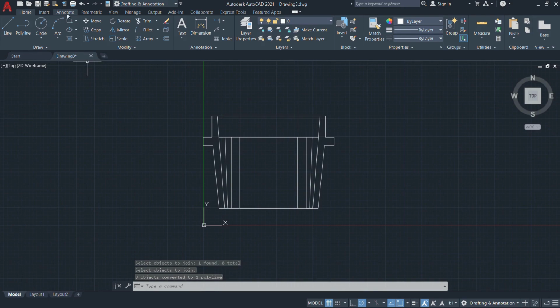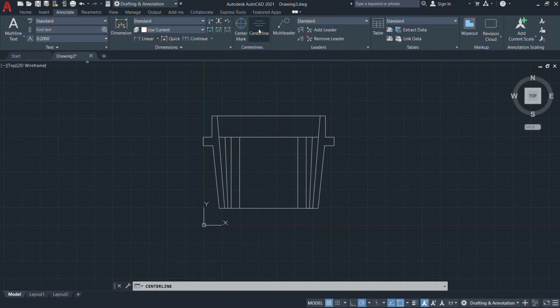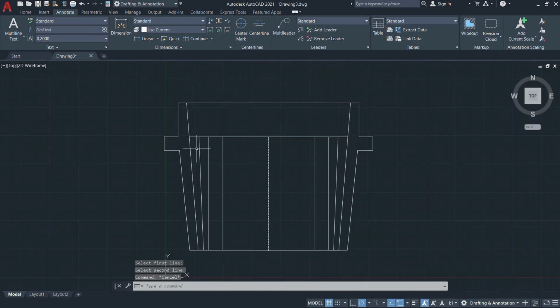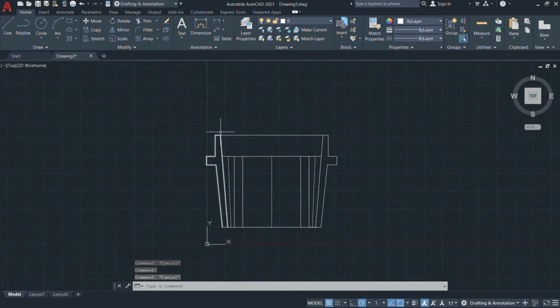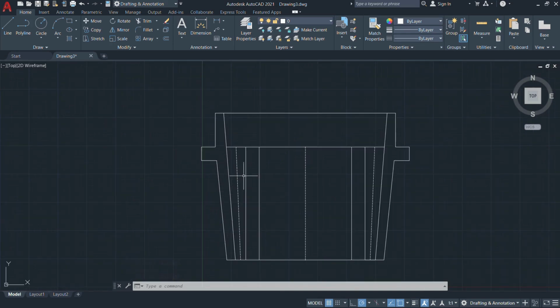Then we can use the centerline parameter. Go to annotate, select centerline and choose two opposite line profiles to create a centerline. It also adds a line format in a separate layer itself. Look at it, here we have another line profile called center line. Then choose two opposite center lines. First one and choose center line now. Because it is a whole body, we need to represent a center line in this area. Almost it is converted. There we have sectional areas in these portions.